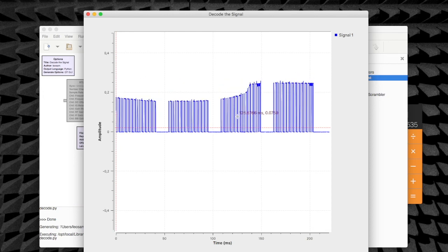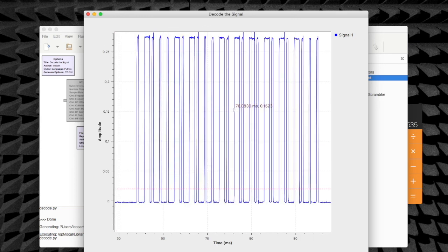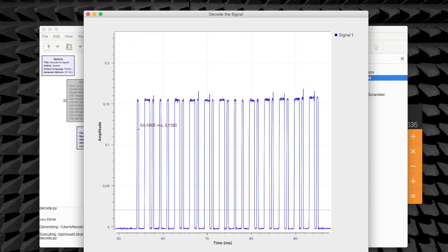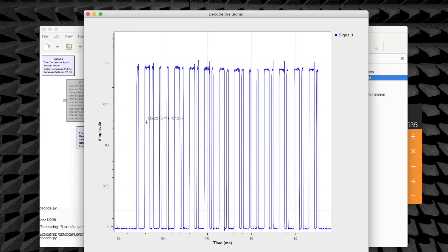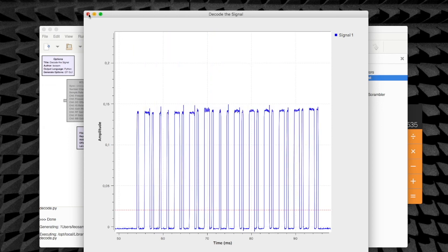That's better. So now we have the signal on the screen, but as you see, this is still not binary as we are expecting to find. In order for us to apply the differential decoding, we need this to be perfectly binary, meaning that the 0 is at 0 and the 1s are at 1 exactly. Instead, we're having an amplitude which is not constant here. If we look in detail at the signal, we see that the signal is varying a lot, but it looks already like something which would be expected as a binary signal, as an oversampled binary signal.